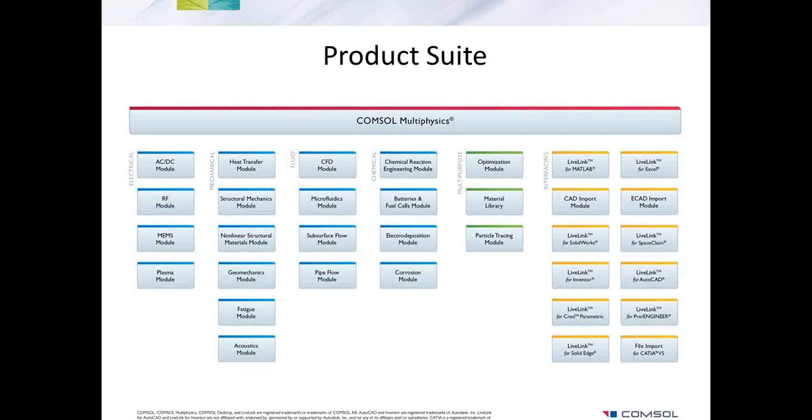Actually, there are certain interesting ways of studying that in COMSOL. We allow what is known as a parametric sweep over your geometry parameters. If you create your geometry in such a way that you have parameterized the geometric dimensions, then you can change the size and geometry of the electrode via a parametric sweep.